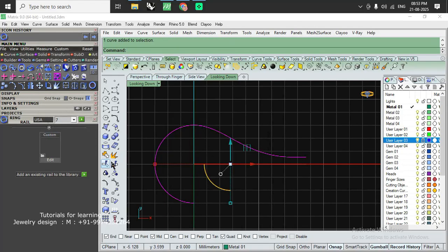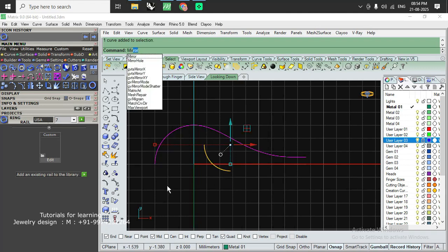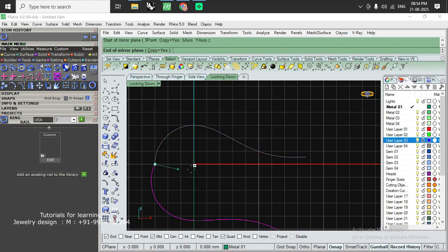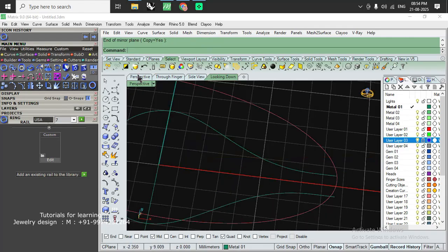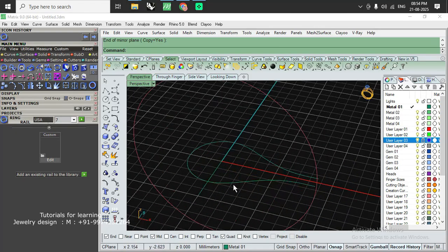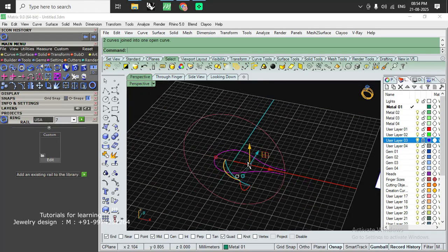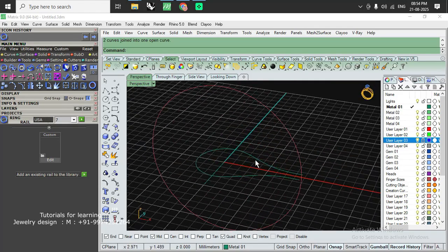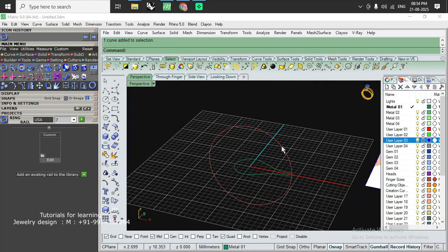Let's select and split option using the point. Let's split it from here. Whenever you can find your mirror option, let's use it because it will create symmetric work. Okay, this way you can create a shape, the knot shape, base shape for the knot. Select and join. Now we can apply curve using two views, curve from two views.